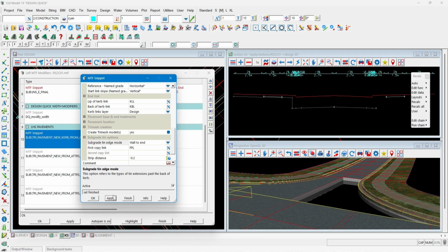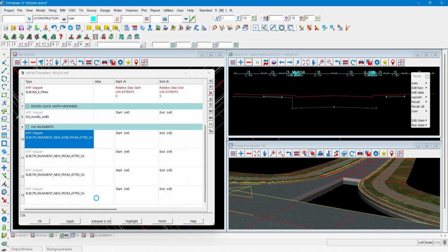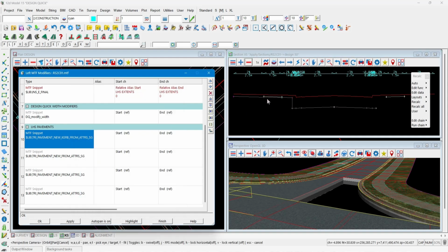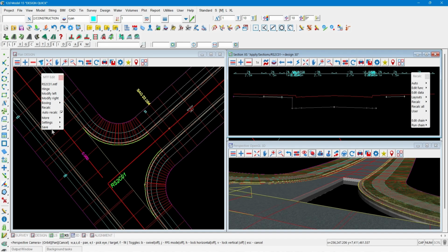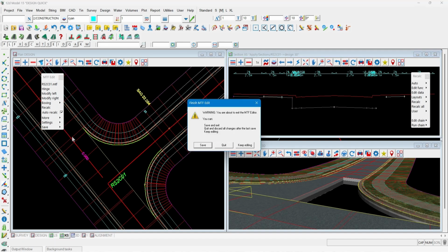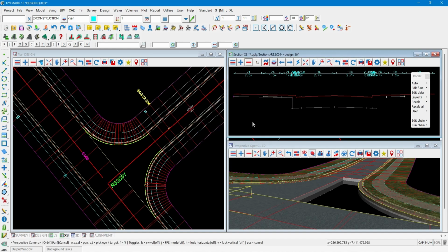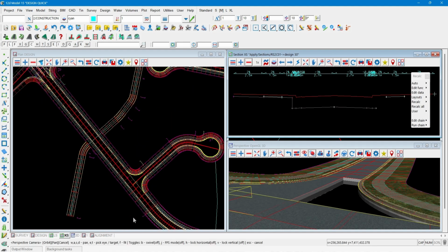So these are relatively new, these subgrade type tri-meshes, but if you're using the design quick start, it will install these subgrade tri-mesh snippets as a default. So we're almost done. One last thing is we've been concentrating on the inbuilt options in 12D that do roads. I did say earlier, you can have a seed file that does anything that you like, and you can use the design quick start either from a toolbar or from this next option.